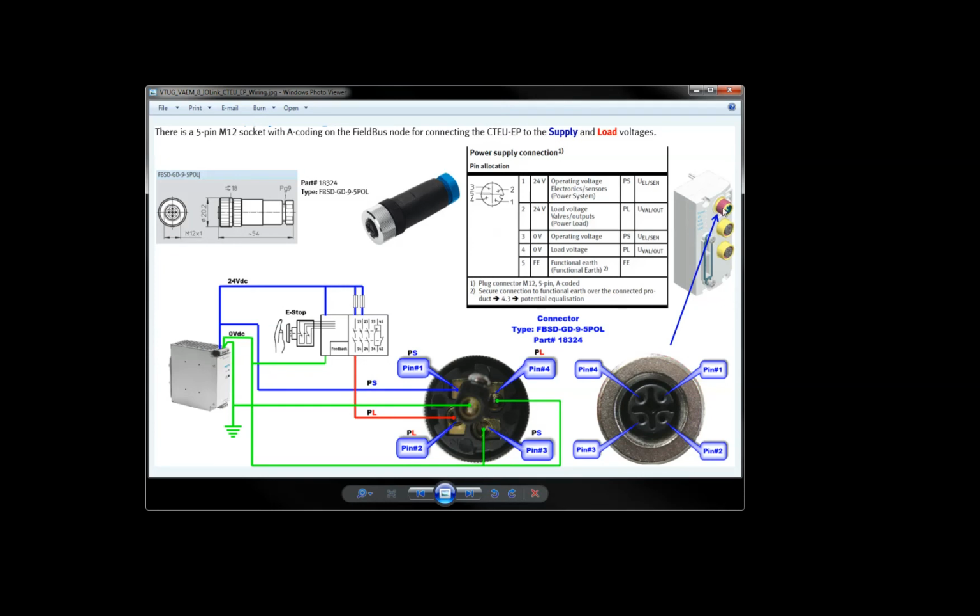And basically, you've got a power connector and M12 on here, and you need to wire this to constant power as well as load power, so that if you have an e-stop or something, you can drop your load power, which is pretty traditional in the world of automotive and other industries. So that's what you have to do for wiring on that.